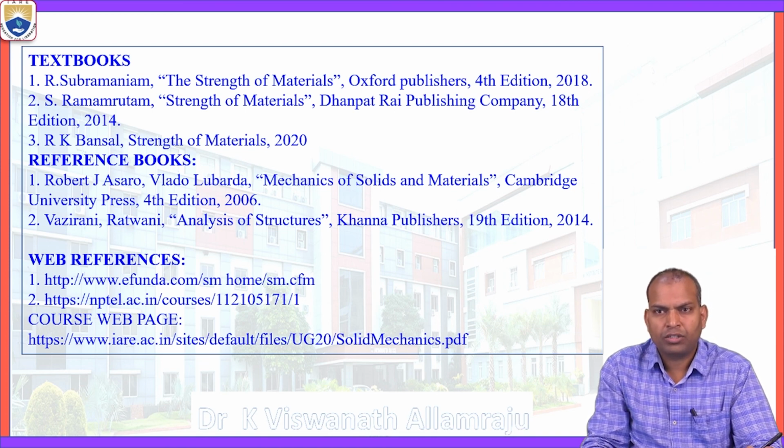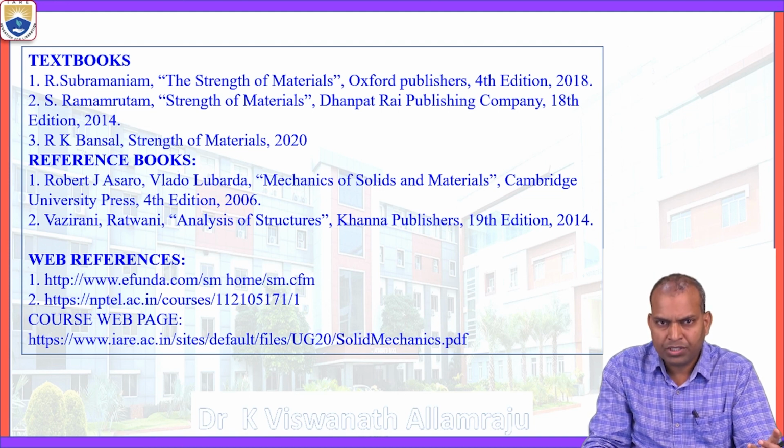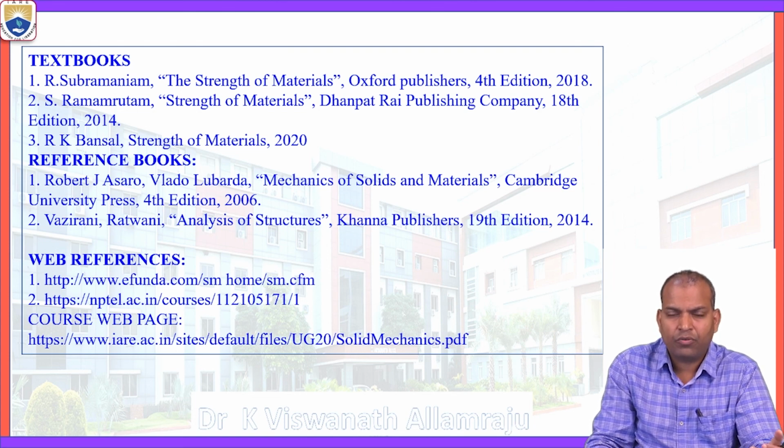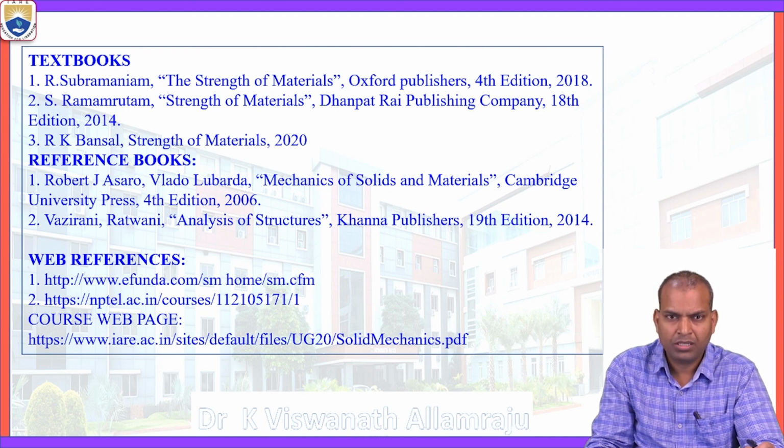With this we can conclude the session. In this session, let us summarize. We have studied what a thin shell is, the definition of a thin shell, and how we can know whether a shell is a thin shell or thick shell based on the internal diameter and thickness of the shell. And we derived the expressions for stresses. In order to fabricate an optimum thin shell, we have to know these parameters: one is the longitudinal stress, another is the hoop stress, and the third is the maximum shear stress. These expressions were derived in this session.